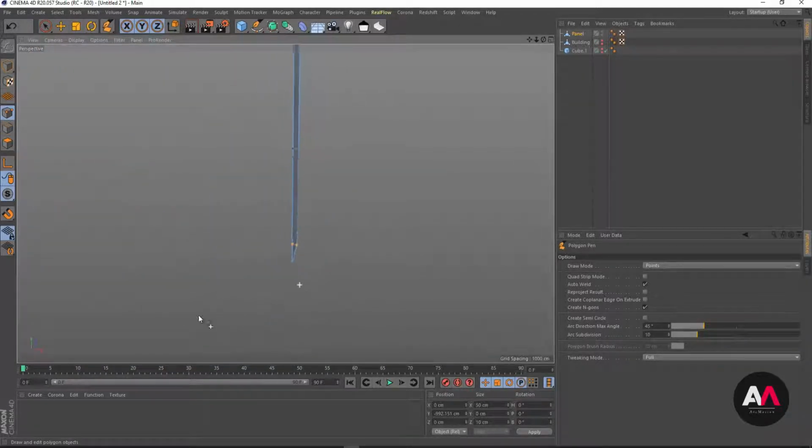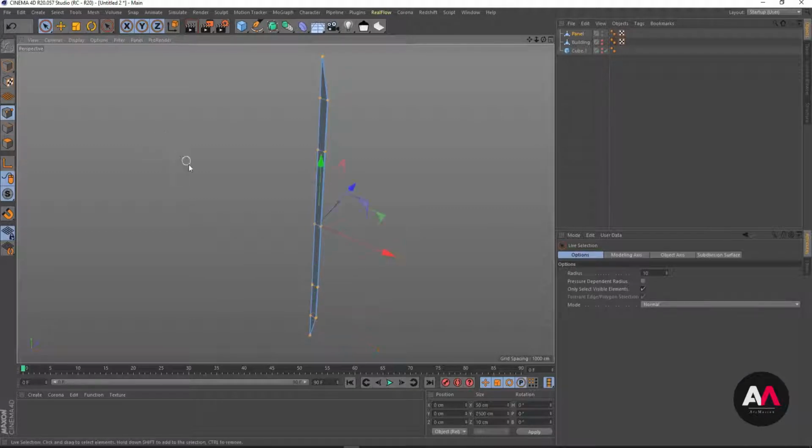Yes, that's good. And it's also important when you do your modeling, and when you're okay with the end result, always to select all the points and optimize them. It can happen that some points are overlapping together, and later on they will corrupt your model in the process of modeling. So it's really important to optimize it. We should do also the same for the building later. We should also optimize the points too.